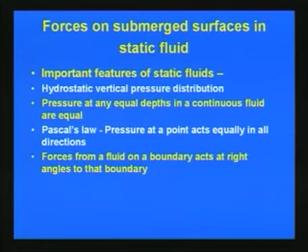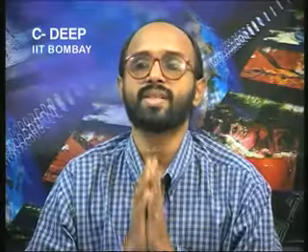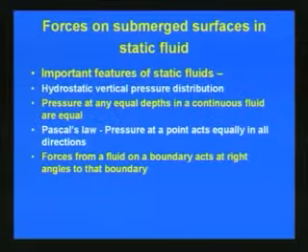So, as we discussed in the last lecture, the important features of static fluids are: the hydrostatic vertical pressure distribution is always assumed generally; second, pressure at any equal depths in a continuous fluid is equal; and as we have already seen in Pascal's law, pressure at a point acts equally in all directions. That is very much valid in all the problems which we are discussing. And the forces from a fluid on a boundary act at right angles to that boundary, as we have seen earlier.